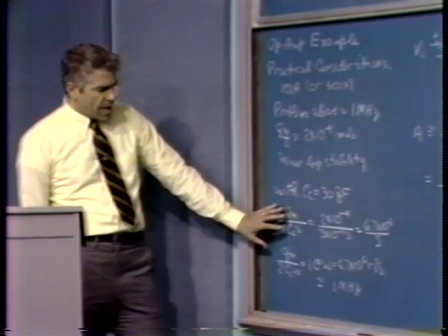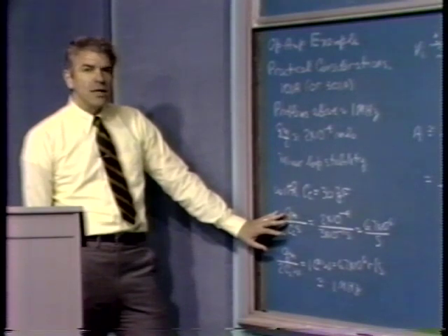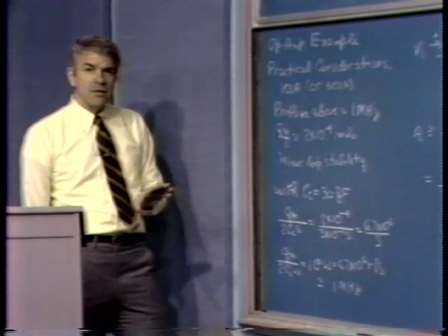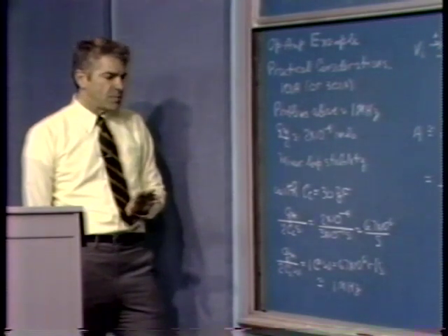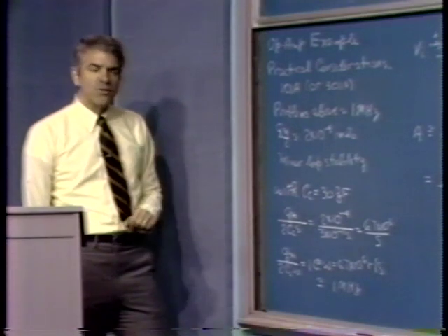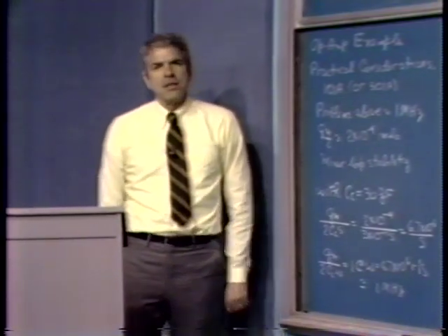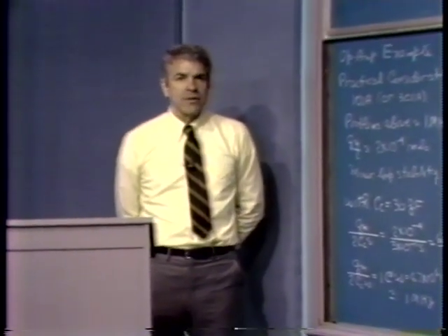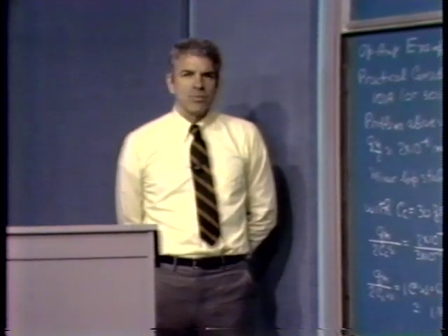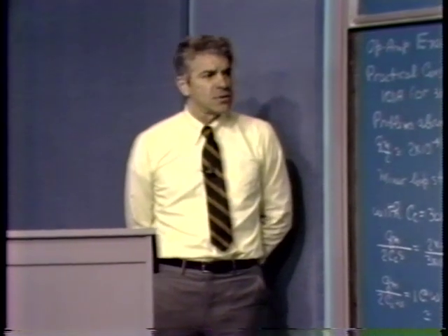So this amplifier, one that uses a 30 picofarad capacitor, is an example of one that will be unity gain stable. In other words, if we form a feedback loop with f equal to 1 by connecting the output of the amplifier directly back to its input, the resultant configuration should be stable, since the major loop thus formed crosses over at about a megahertz. The problem is that that sort of compensation is overly conservative in many applications. It's fine if we have direct feedback from the output to the input, but it really deteriorates the dynamic performance in many, many other feedback configurations.